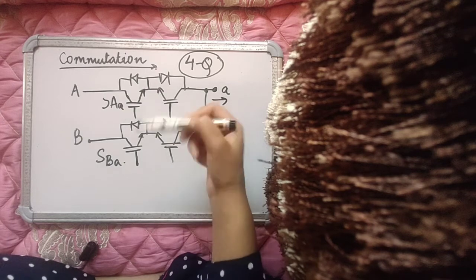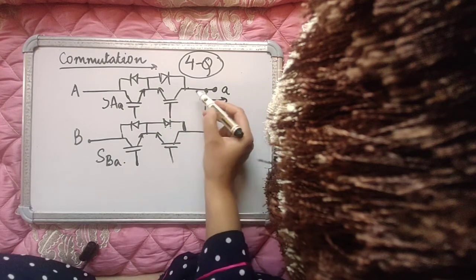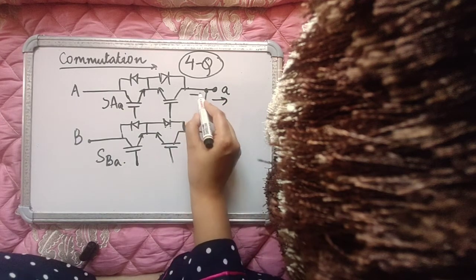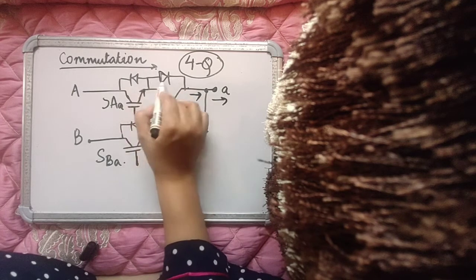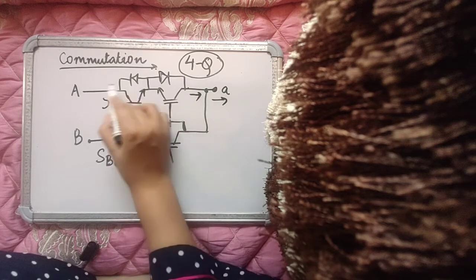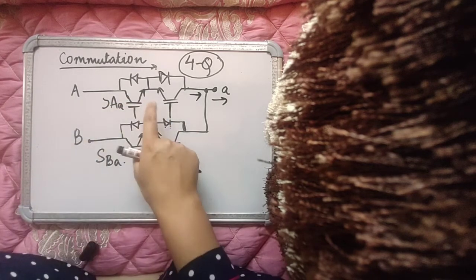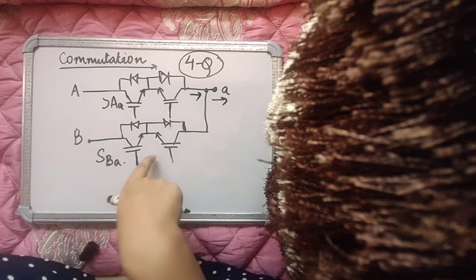Neither this is on, neither this is on. दोनों में से किसी के पास pulse नहीं है. अगर current positive है तो वो कहाँ से जाएगी? The diodes are not connected that they can carry any current. They're connected back to back. You need the current path to be through a switch. So there is no freewheeling path in a bidirectional switch.